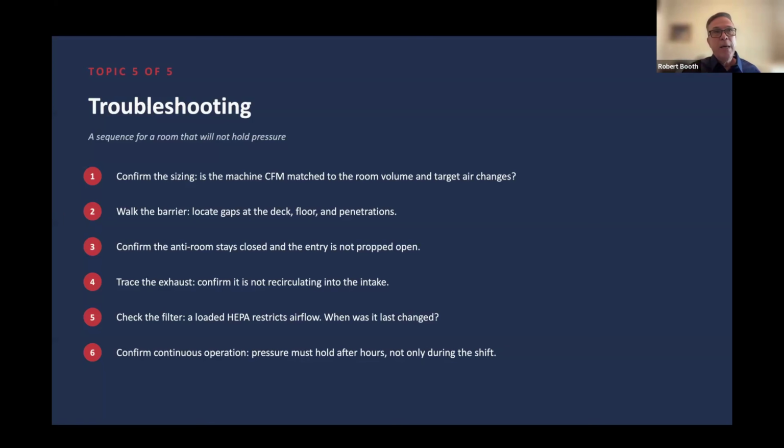The next order is indoors to an unaffected type area, such as, I can recall doing an actual OR project, and we relocated the exhaust to a solid utility room or to another room in a mechanical space because that was a lower hazard. And we just didn't feel comfortable blowing this into a corridor of an OR. And sometimes you can't avoid that. We do that with the ECU units. They have to HEPA filter, and we're putting the ECU units up in like an ICU or whatever. And then the last, which is what we try to avoid at all costs, but we have to, and that's exhausting into the occupied space because we know there's so much potential.